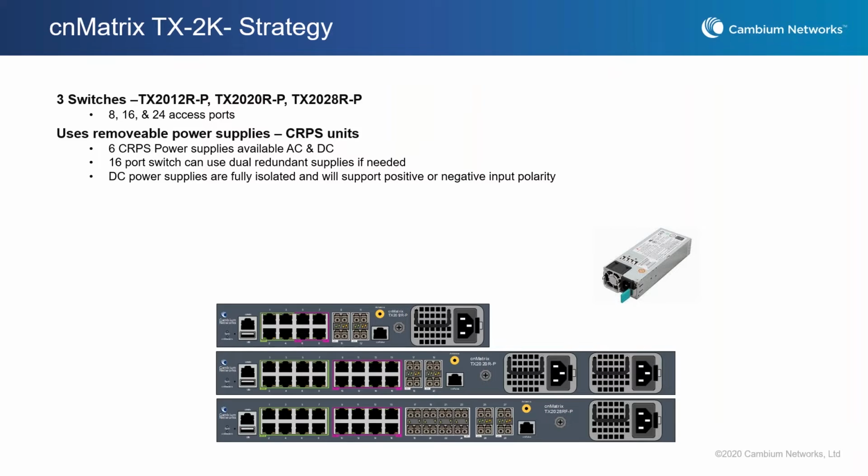You will get a notification. You will get an event that one of your power supplies has failed, and then you can, at your convenience, swap out that power supply for a new one. Probably the most popular question I get is, do we support negative 48 volts? Yes. So these power supplies are fully isolated, and we will support positive or negative input polarity.